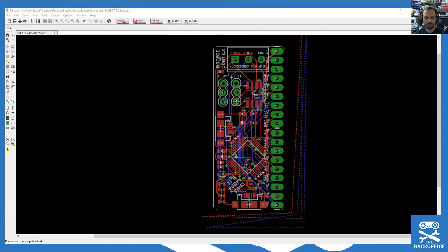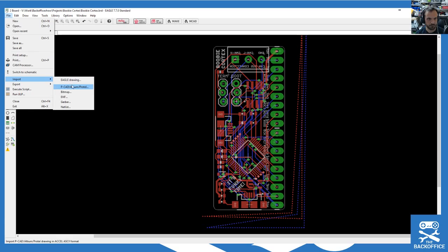If you're ever doing your board at home, by the way, don't lay it out with the pins on the side here. That was a mistake on my part this time around. It's really not worth it, for this exact reason, that you have to rotate everything.